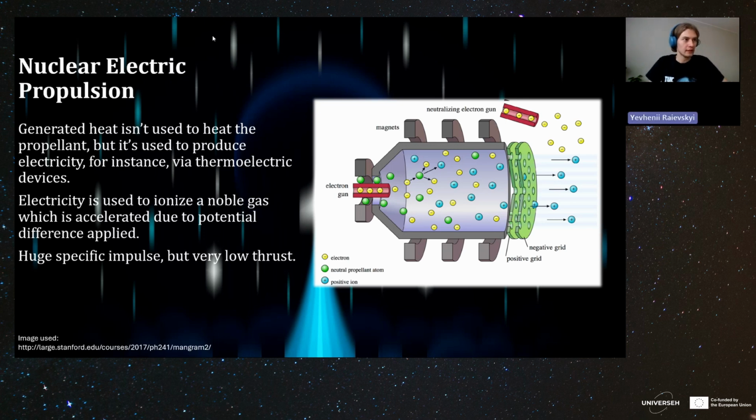Okay. The most common electric thrusters use ionized gas, as I said. For example, an ion engine uses electrodes or electromagnetic fields to push ions to exhaust velocities of 20 kilometers per second, far higher than any chemical rocket's exhaust speed. The specific impulse of electric thrusters is measured in thousands of seconds, typically even 3,000 or 5,000, so it's a huge amount, basically. The trade-off is thrust.